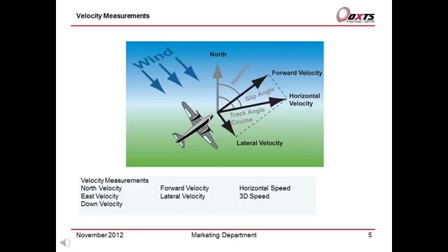The RT measures true heading, so it is possible to separate forward velocity from the lateral velocity to give horizontal velocity. In the example here, the aircraft is flying straight into crosswind. The track or course over ground the aircraft takes is not the same as heading because of the crosswind. This is the same effect as slip angle in cars.